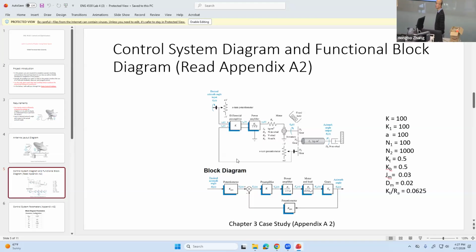But our idea here, instead of relying on P control, is to do state space. The whole idea is you model the entire preamp, power amp, motors, and gears as the state space. Then you do pole placement to do good control.